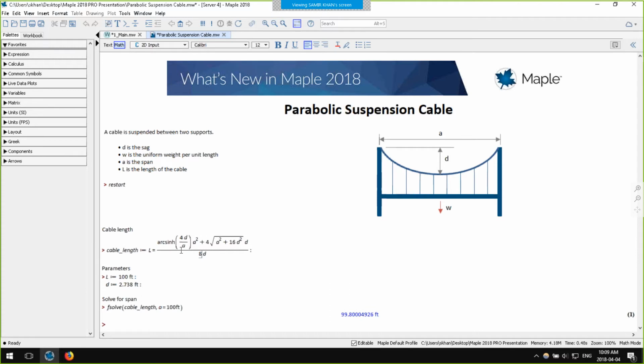There are a number of parameters in this equation, including D, A, and L. Here I've specified values for L and D, and you should note that these parameters have units associated with them. And now I can put this equation into fsolve and ask fsolve to give me a value for the span. Let's just run this worksheet. And the result pops out with units associated with it.